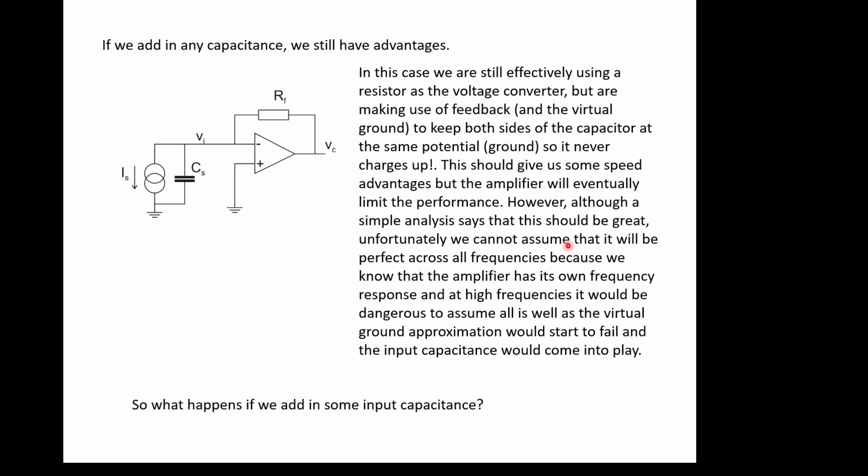However, although a simple analysis says this should be great, which is just what I've been telling you, unfortunately we cannot assume that it will be perfect across all frequencies, because we know that the amplifier has its own frequency response, and at high frequencies it will be dangerous to assume that all is well, as a virtual ground approximation would start to fail and the input capacitance will come into play. Right, now that's an interesting point.